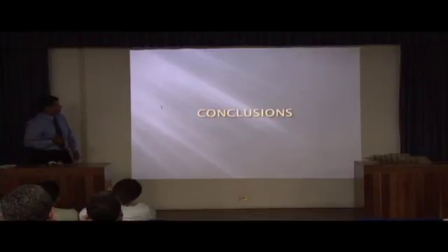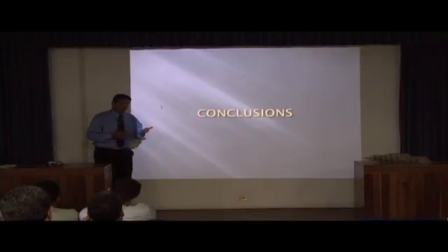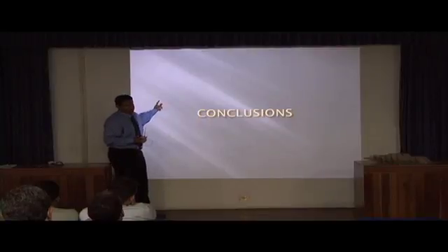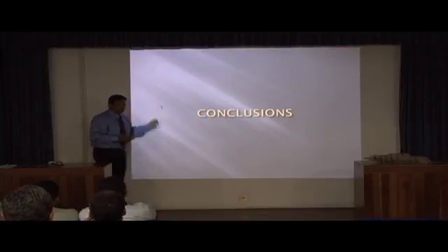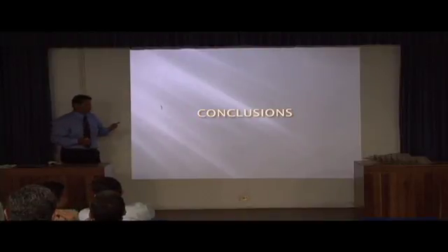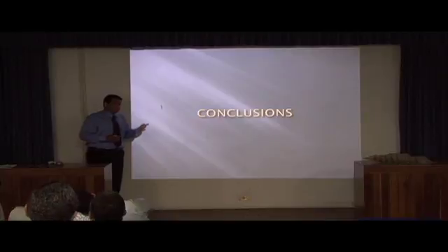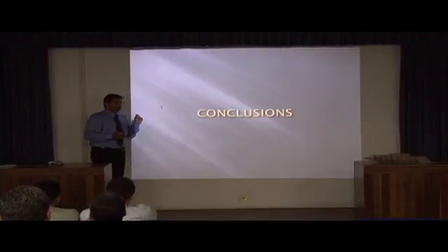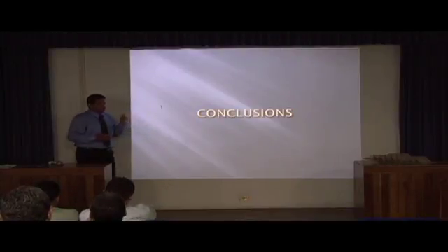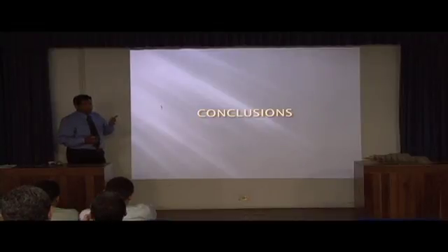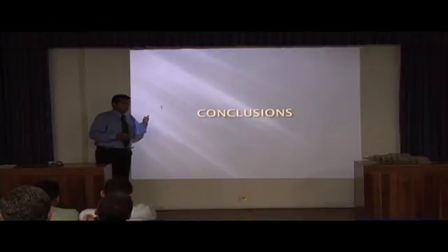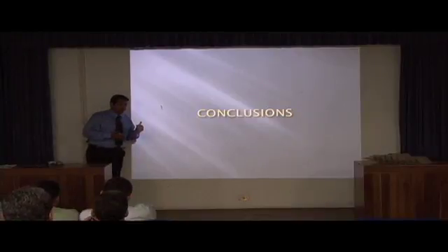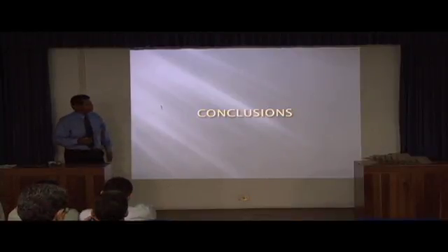Finally, to compare, to reach the last objective, we must compare all the stresses and displacements with the reactions, with the thickness of 3, 2, or 1 centimeter. We can see that the worst condition is with 1 centimeter. The highest displacement here is 0.5 centimeters. The highest stress is 244 kilograms per square centimeter, which is much lower than the yield stress of 2400 kilograms per square centimeter.